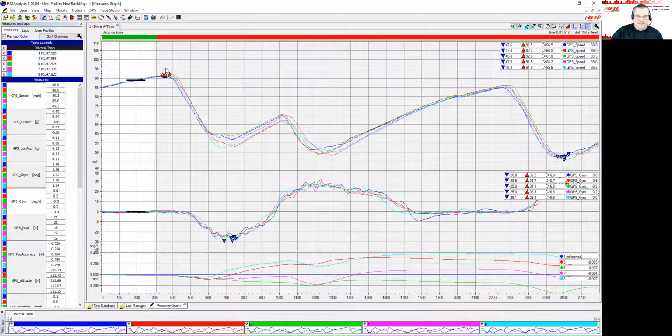What I'm going to do is look at my data file here, and these are all peak miles per hour. So clearly I'm always hitting the brakes a little bit earlier here. Look at the exact traces, bring your cursor in, and find the spot, with all of your laps and typically the way you drive in your car, where you're hitting the brakes. By putting the cursor there, you end up with a number up here that says 327.8. Let's just call that 325 feet. That is about where I know I'm always still on the throttle, and it's staying away from this transition.